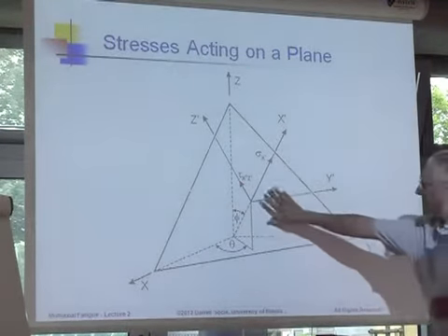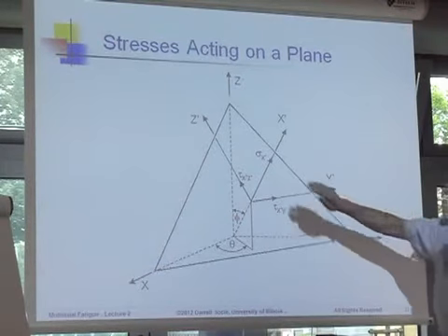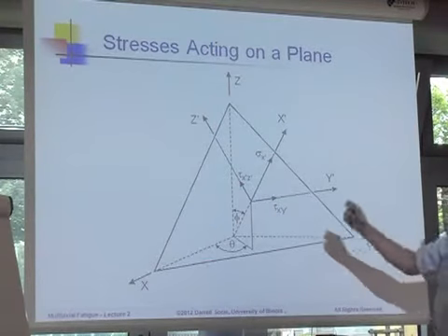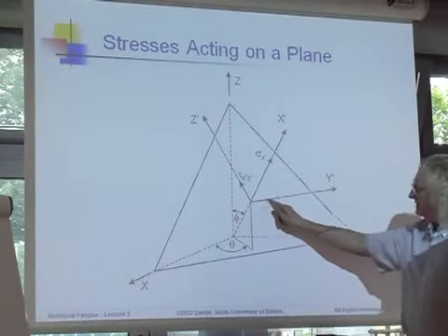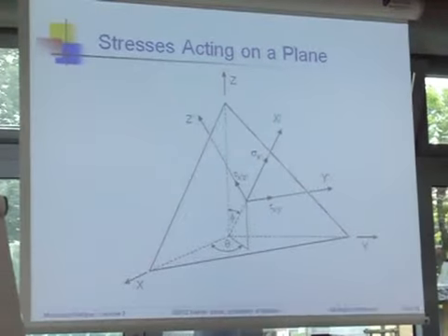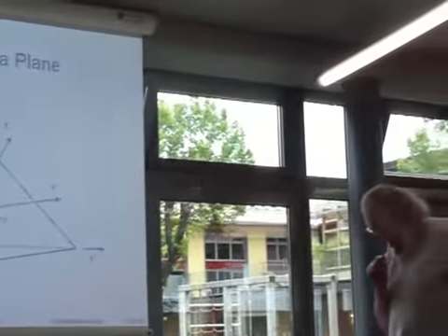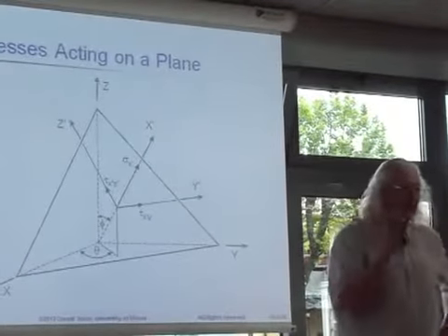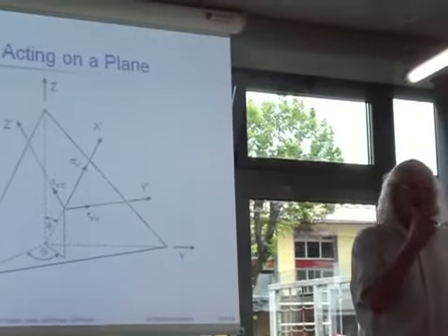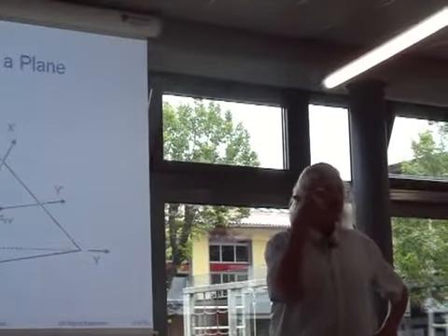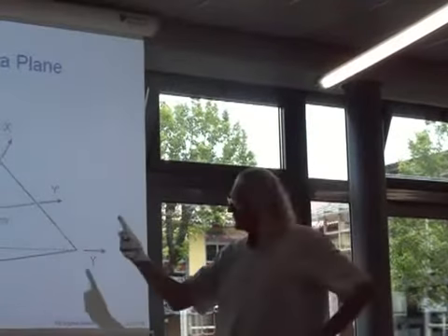So we look at this plane, and then we, of course, have a normal stress in this direction. And we also have 2 stresses of tension nature which are in the plane, but they are unimportant in fatigue. They are unimportant. I'll show you that later. And then we also have 2 shear stresses. And there are 2 shear stresses only because of the mathematics. Right? We like to think in an orthogonal coordinate system. And then we have 2 shear stresses.